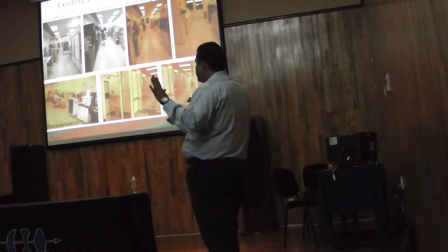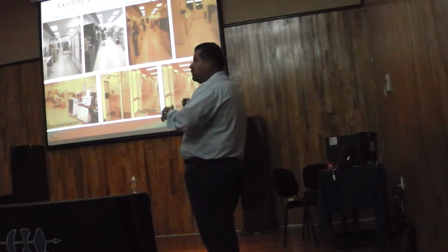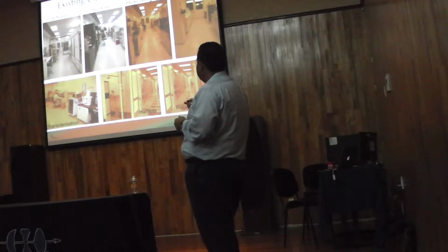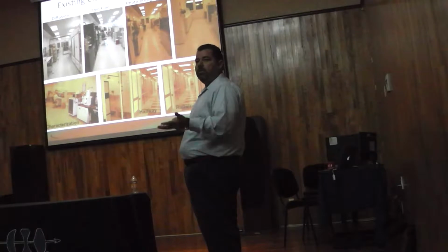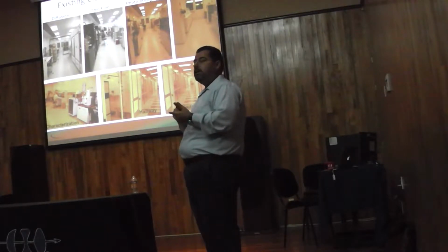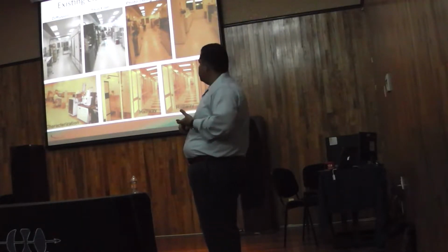We have 5 bays, we call it, so 5 sections. The first section is a diffusion. In this diffusion section, we do a lot of thermal treatments. We grow silicon oxide, silicon nitride. We can dope silicon as well.